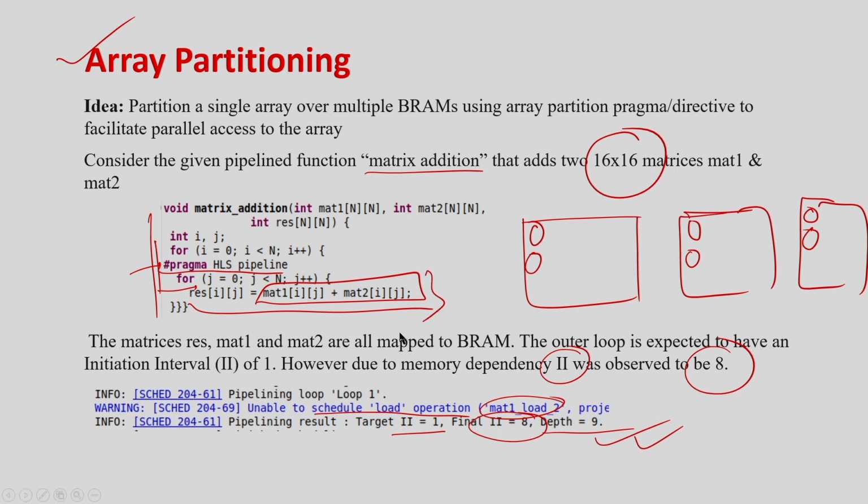This is going to unroll, right. And if you unroll, you can understand that there will be so many memory reads, and because of that you are not getting this initiation interval of 4. But because these operations are element-wise multiplication, it is a symmetric access.